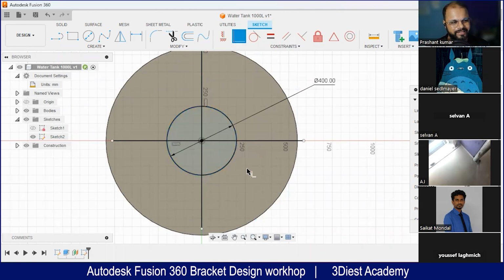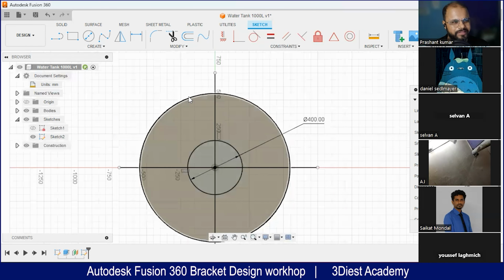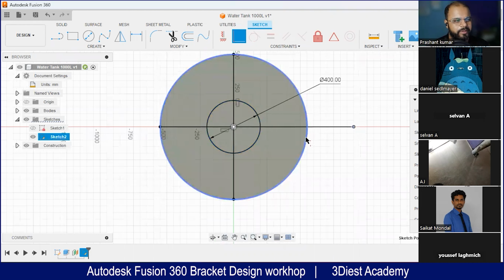And now, since the lengths of these lines are not defined, I can extend these lines by any amount, since those are not constrained. So to make those lines constrained with the outer diameter of this circle, we can use the coincident constraint again. So I will activate the constraint. This time I will select the perimeter of the bigger circle and then this point, boom. Perimeter of the bigger circle, then this point, boom. So you can see I'm just constraining my sketch, so it will be defined.